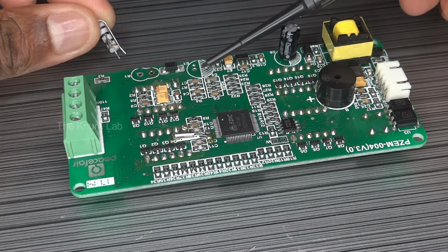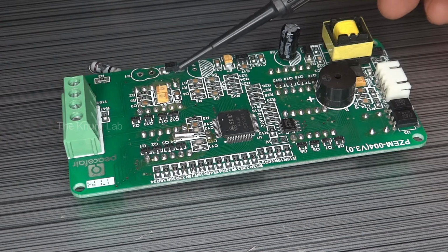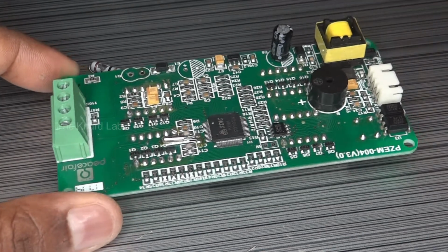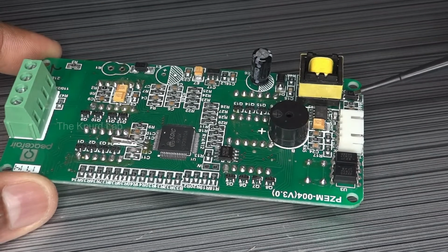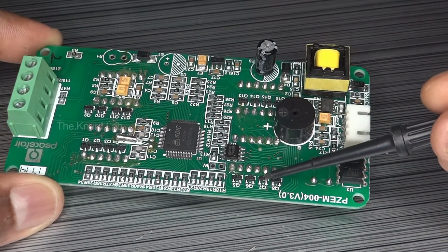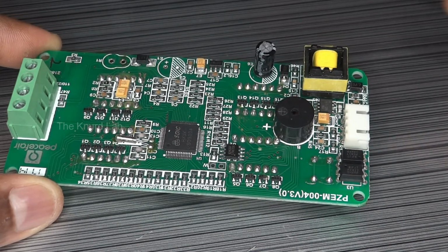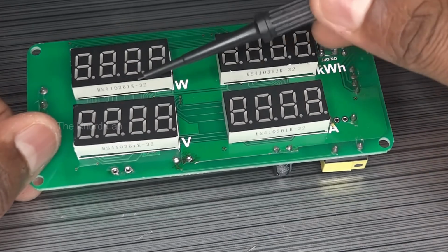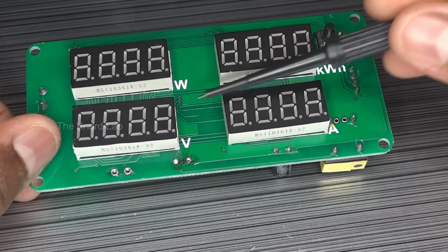This must have caused a short because its aluminum casing landed on a component, creating a short circuit path that led to the AC mains dumping its current into the sensitive components, thus frying them. Had the design included a simple fuse for short circuit protection and a varistor to arrest the voltage spikes, this could have been avoided to a certain extent. At this point, I realized any attempt to repair it was just futile.